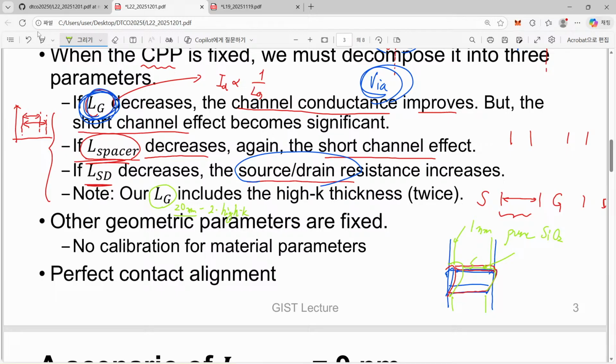So we must consider that the actual gate length is even shorter than our current calculation. In our example structure we must consider minus 2 nanometer for the actual metal gate length from the drawn dummy gate length. So 20 means that actually 18. When I say 10, it corresponds to actually 8. Okay, so please understand.